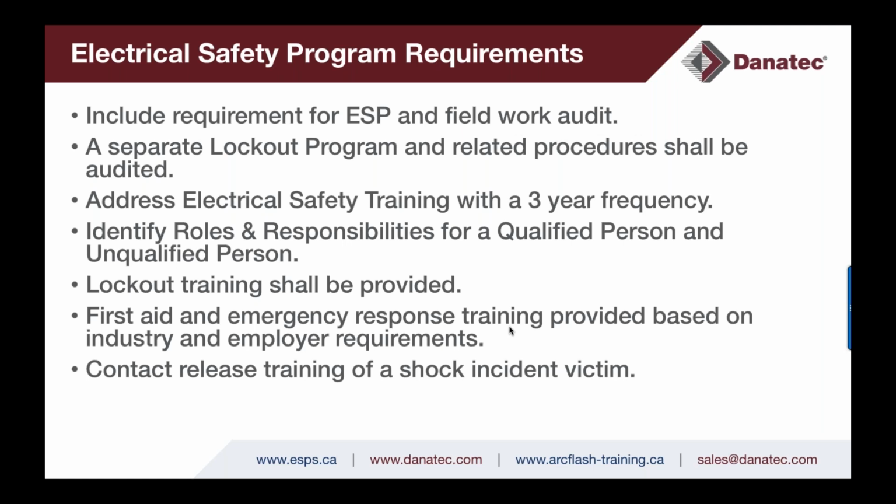Now, in the 2018 editions of 70E and Z462 related to establishing an electrical safe work condition, the lockout requirements were moved forward in the standards and embedded in Article 110 and Clause 4. So a separate lockout program, and this is another good point, the electrical safety program is not a lockout tagout program. There should be a separate lockout tagout program as part of the overall occupational health and safety management system. So the electrical safety program will use that lockout tagout program in implementing the requirements of establishing an electrical safe work condition. Some training requirements, and on this note, the lockout tagout requirements for training and auditing have moved into, again, Clause 4.1 and Article 110.